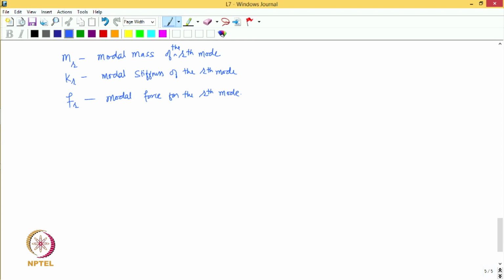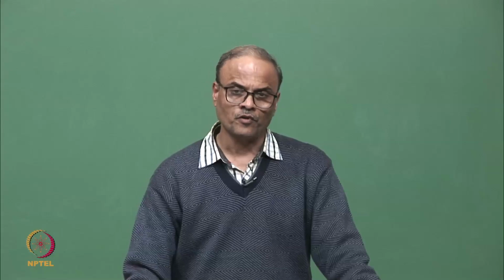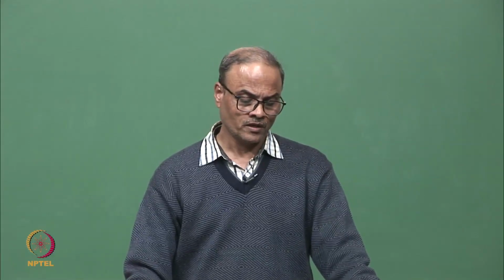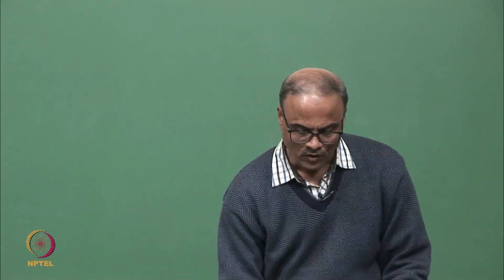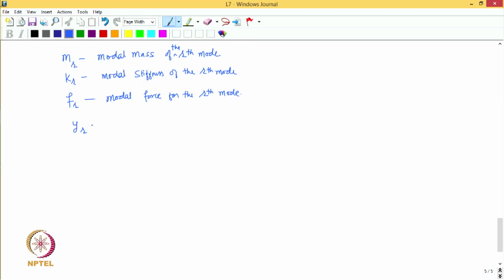So, before we solve the rth differential equation and other differential equations corresponding to all the modes, we can further give a physical interpretation to the responses we obtain from these differential equations. So, yr basically tells us the response in the rth mode of vibration, and that is why this is referred to as modal response.